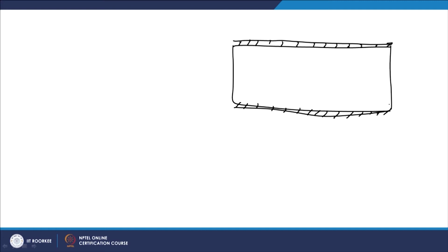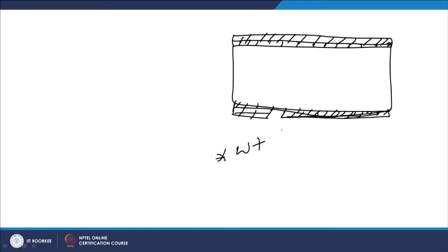So, in order to decrease heat transfer, it is always favorable that the thermal barrier coating thickness is great. Very thick coatings of TBC materials can be applied in situations where weight is not a big issue.